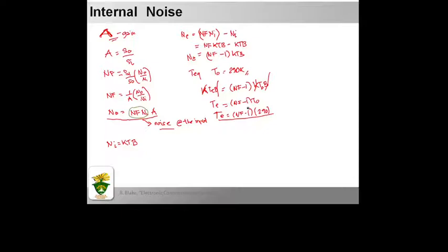It is possible to get an equivalent noise temperature of the whole system by simply adding the noise temperatures of the antenna, transmission line, and receiver. From this, we can calculate the system noise figure by rearranging.